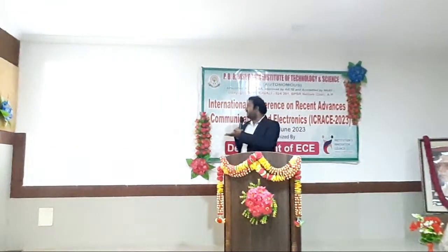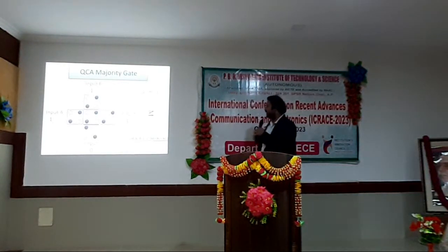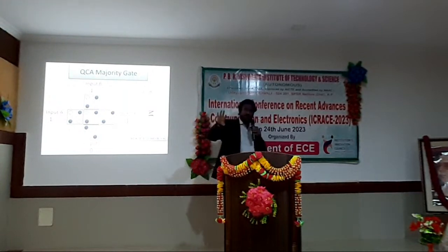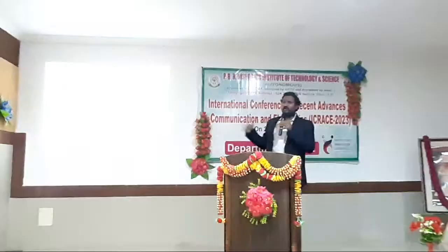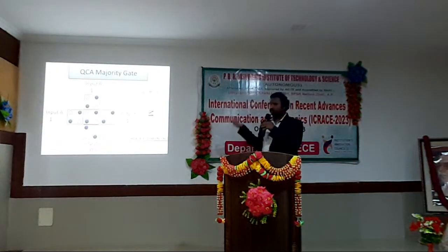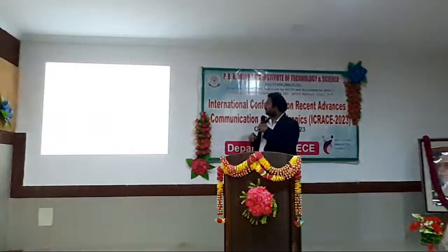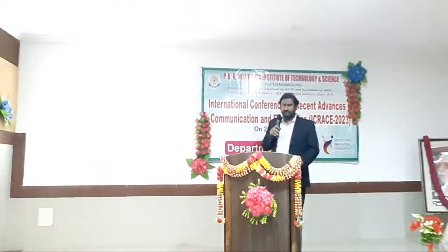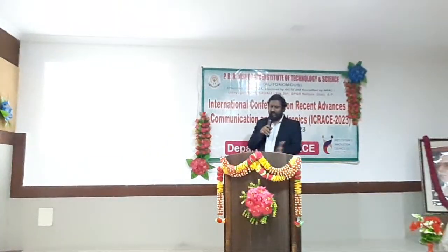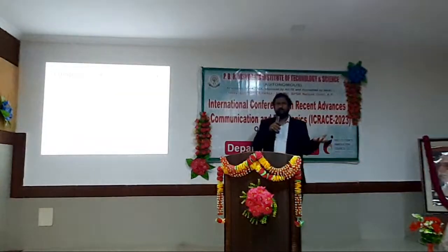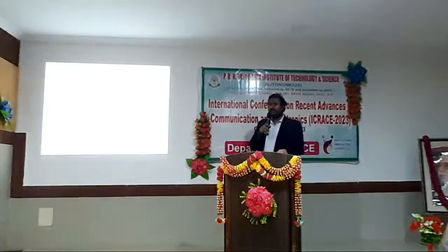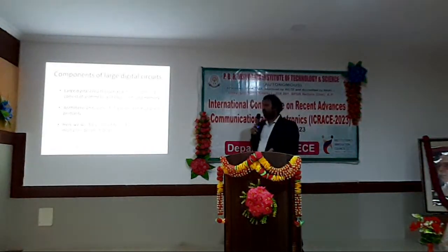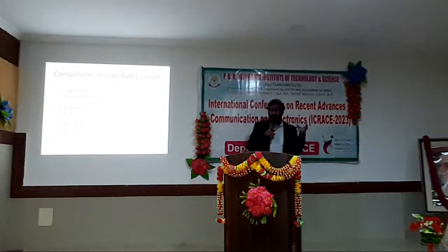By using this majority gate, we can make an AND gate as well, as in this logical equation. You make one input 0, it becomes an AND gate. You make it 1, it becomes an OR gate. So our traditional gates can also be realized using this. The main challenge is that realizing this circuit is very difficult. It won't work at room temperature. It should work at sub-Kelvin or Kelvin level. That was a drawback, but recently some people have started fabricating room temperature quantum dots.